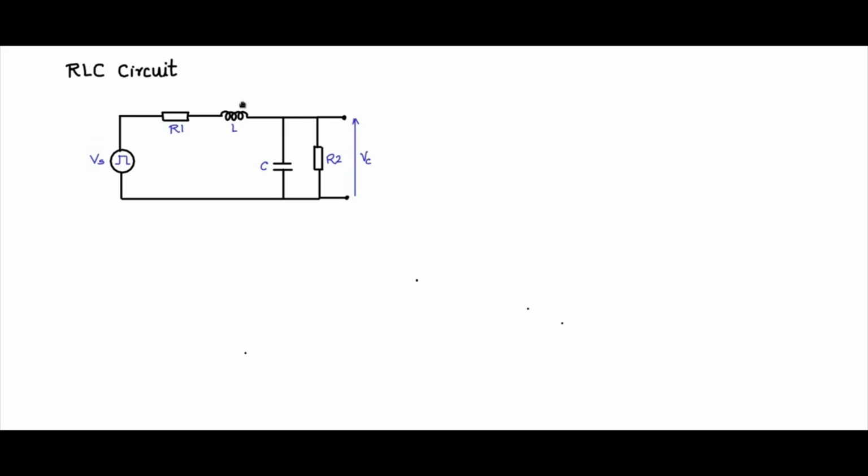And now let us write down the equations that represent this circuit. So now, first, let us say that a current IL is flowing through the inductor. So inductor current is one state variable. Always the variables associated with energy storage are considered as state variables. IL is inductor current, it's a state variable. Voltage across the capacitance is also a state variable.